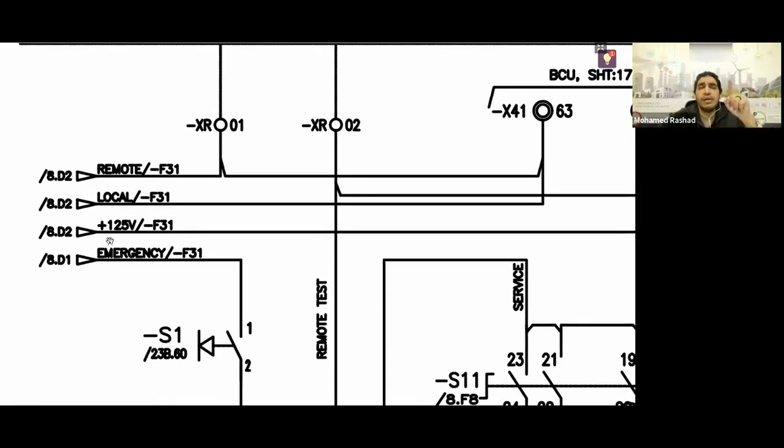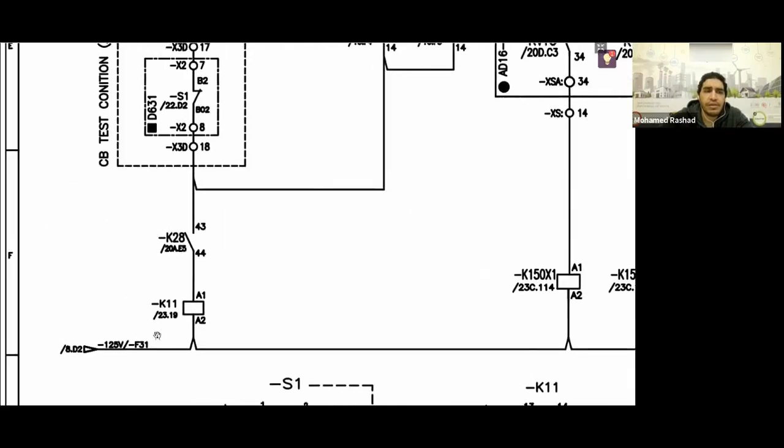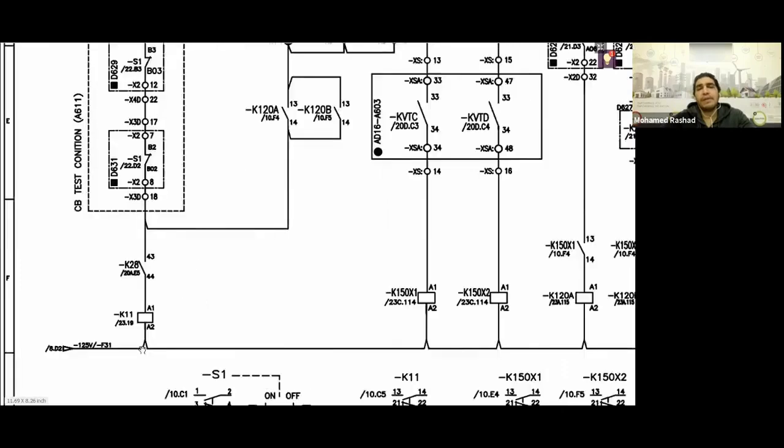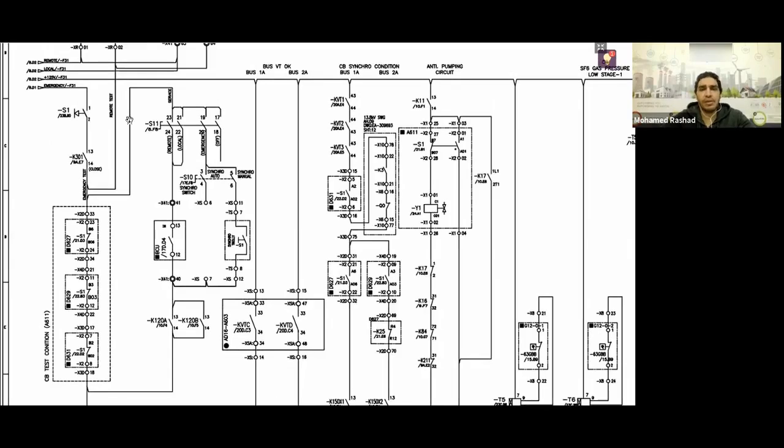And you had 1 direct positive, which tells you what, right? And here is the negative, located at the very bottom, which is where? In 10F1, page 10 that we are on, and here is F, which is the row, and 1, which is my column. All right, great. So this is my negative. Okay, you have the negative present in the entire circuit. Only the positive is supposed to be there, right? Let's take it easy so we can dissect this circuit easily.